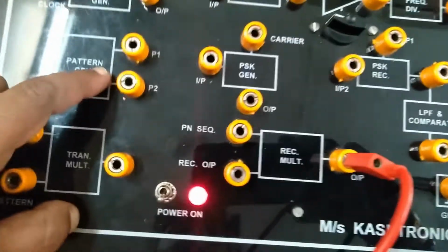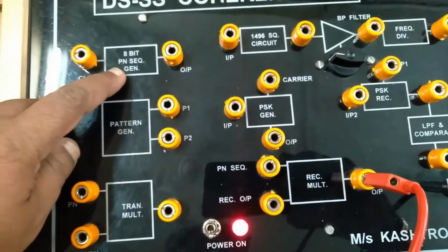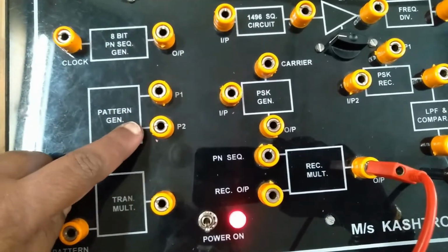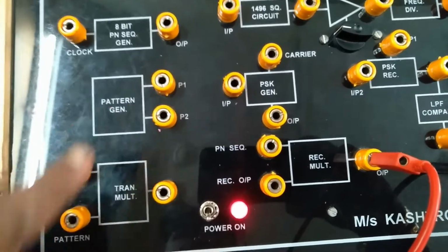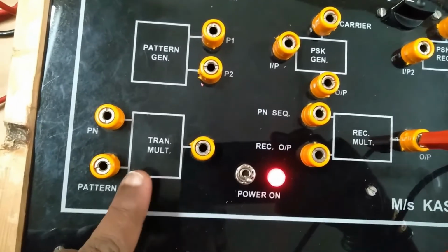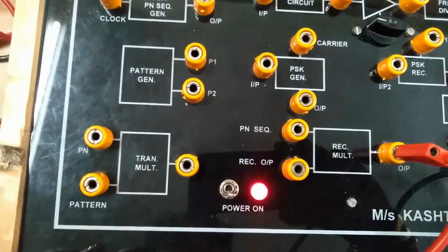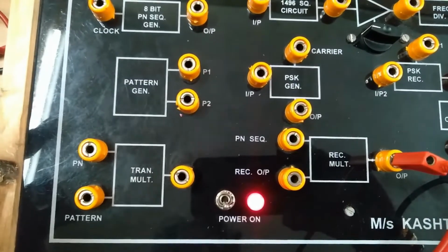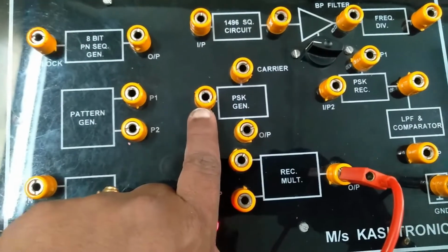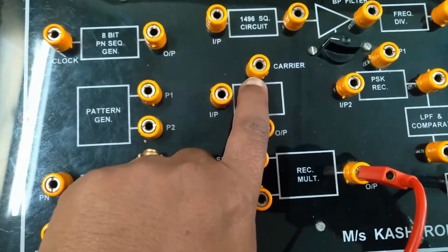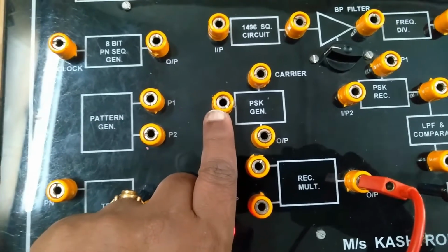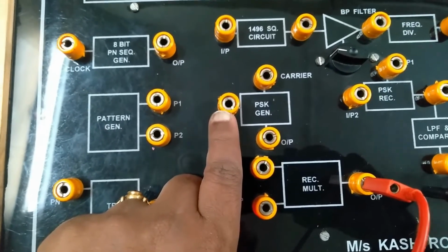But now you are transmitting it with the help of a PN sequence. If I say the PN sequence frequency is now 2k, it is added with the 1k. Why am I adding the frequency? Actually it is a multiplication in the time domain, and multiplication in the time domain becomes convolution in the frequency domain. In convolution we know that we add the frequency components. So it is 2k plus 1k, that is 3k, which has been added. If I give this 3k as an input, and the carrier is going to be 20k, so 20k carrier plus Fb, now 3k, so it is Fc plus Fb, 20 plus 3, that is going to be 23k.